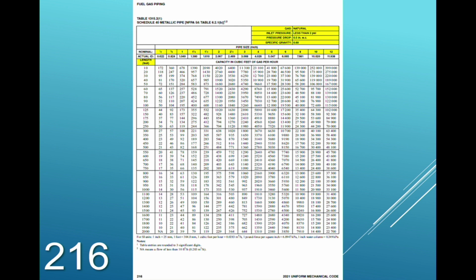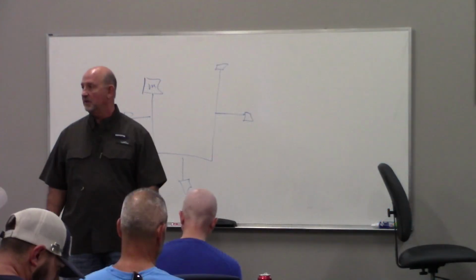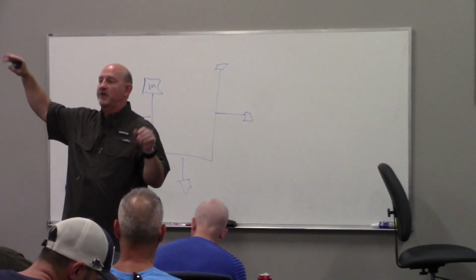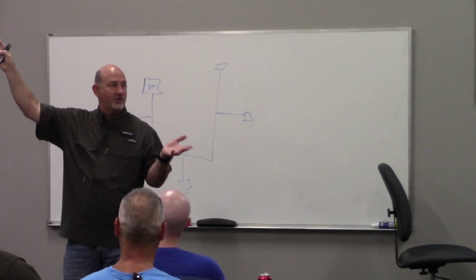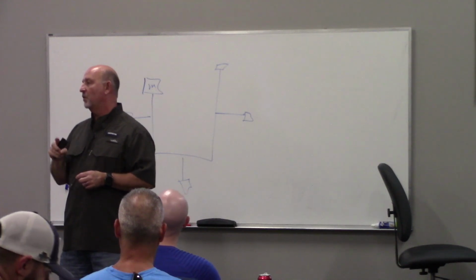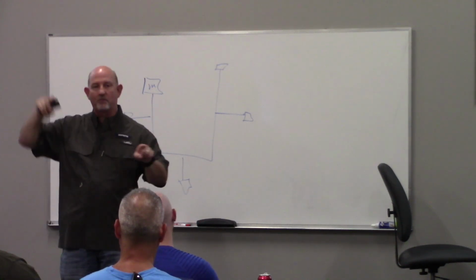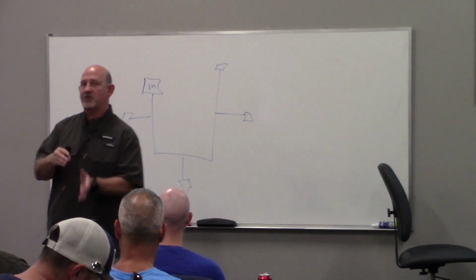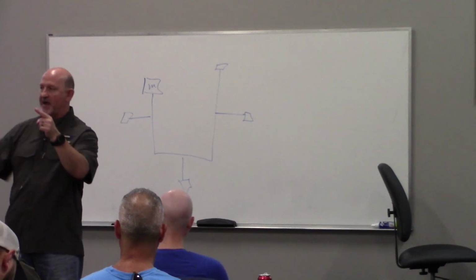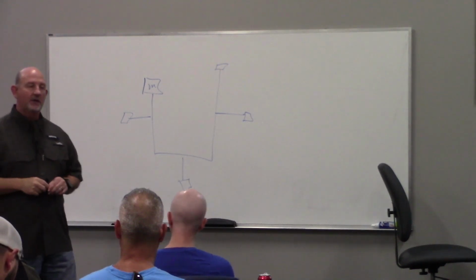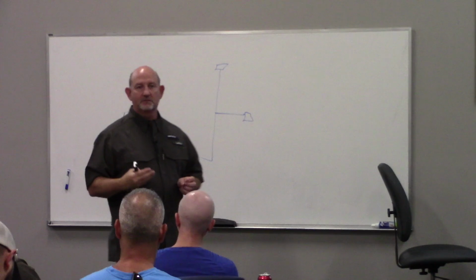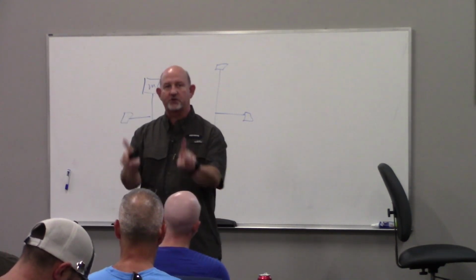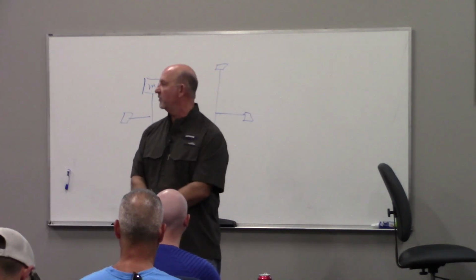So, again, sizing gas is pretty straightforward. A couple of steps, we go from the meter to the furthest point. The furthest point is the furthest point because it's the furthest point. That's it. Furthest run ever. And then, remember, we only measure the distance to get to the furthest point. We don't add the branches to that because the gas is not going to go in and out of I and in and out of H and in and out of G, right? It's just going to take the path of least resistance to the furthest run. And then, for every piece of pipe you look at, which fixtures is this pipe alone feeding? If it's feeding one fixture, then that's your total demand. If it's feeding two fixtures, then combined, that's your demand, right? That's all there is to this. Very straightforward.